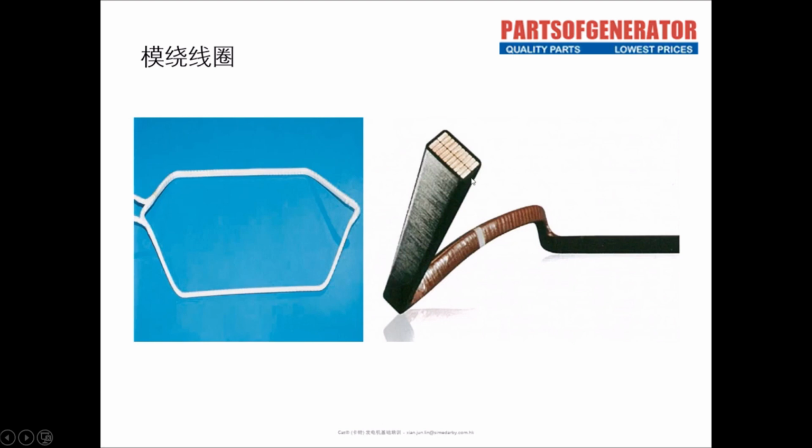This is a mold wound coil that has not been embedded in the wire trough. Each turn of this mold wound coil is pressed with a mold. This is the coil we use. This cross-section is made up of square copper strips neatly stacked together, and then wrapped with an insulating layer. This insulating layer is usually tied up with mica tape. We know that mica is a material with very good insulation properties. So this mold wound generator has better insulation and can withstand higher voltages.